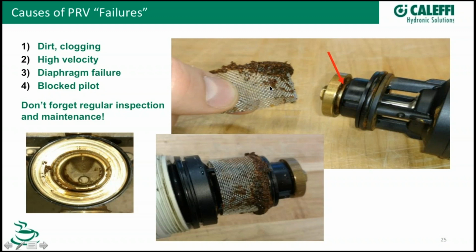Now the screen's going to get as much as you can. Obviously, you can't make this too fine a mesh. It would plug up instantly. So there's kind of a balancing act there on what mesh we use to give adequate protection and still not plug up with just solder flux or something that could completely plug up the screen. So I think we got a pretty good balance on the size of our screen for the job that we're trying to do. And you can see down here where some of the debris is sitting in the bottom of the body there too.